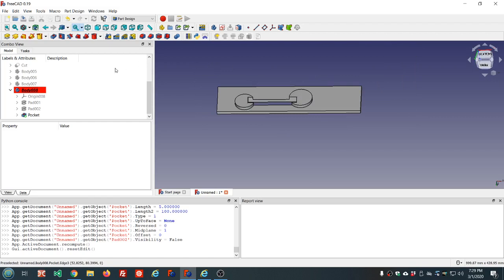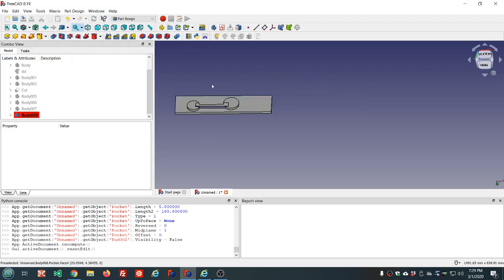If you do, it's two different bodies. You do the Boolean on two different bodies. Otherwise you just use the additive or subtractive features, or additive or subtractive primitives here, or do the Boolean on two different bodies. So like one is your active body, click on it and then add another body to it.